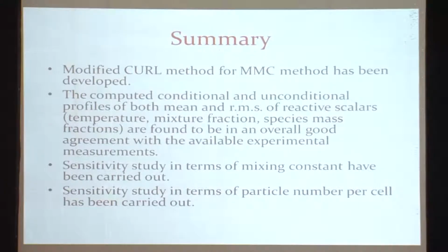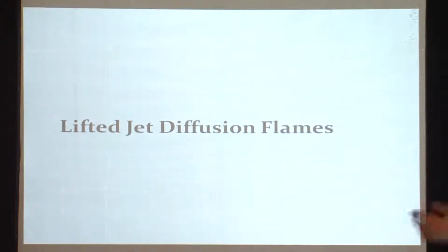So in summary, this modified curl method for the MMC method has been developed for the pilot stabilized flame, and the computed conditional and unconditional profiles of both mean and RMS of reactive scalars are found to be in overall good agreement. We have carried out a sensitivity study with different mixing constants as well as particle numbers. So next we have moved to the lifted jet diffusion flames.